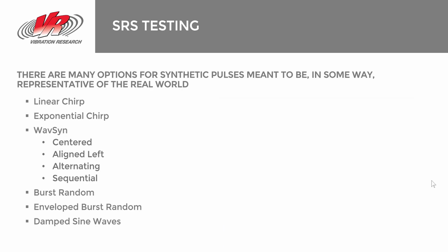So once we have the SRS, the shock response spectrum, this qualification or this level of maximum acceleration that our product will exceed at these frequencies, we need to then synthesize a pulse, typically, that will exhibit similar frequency response characteristics as the environment that we are analyzing. And there's synthetic pulses that can be used.